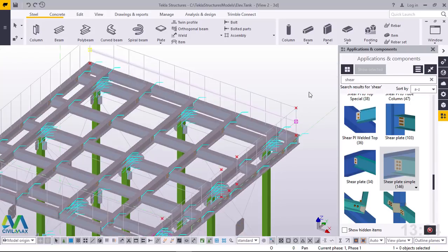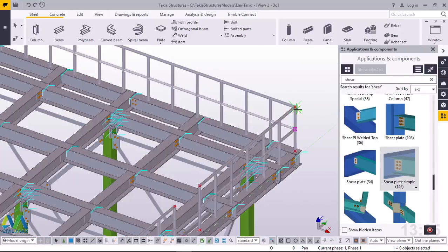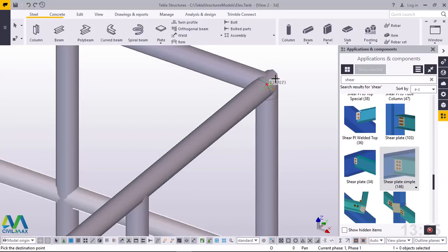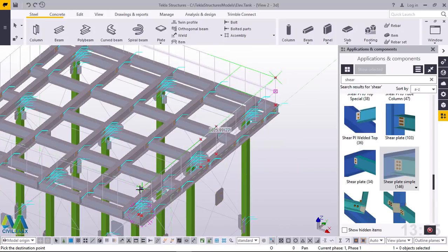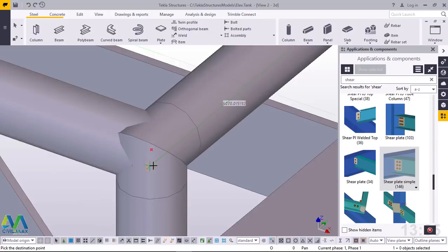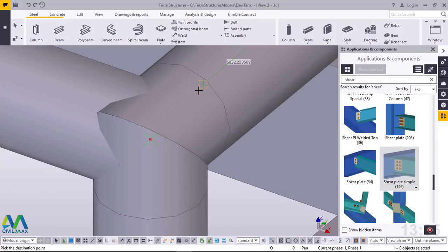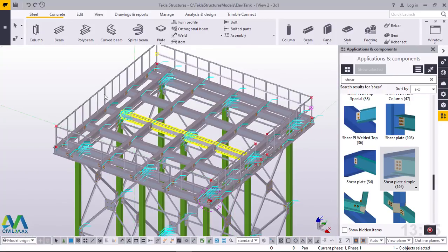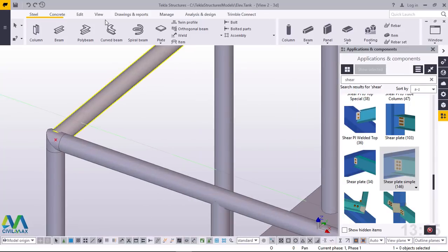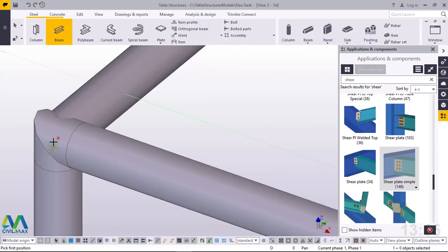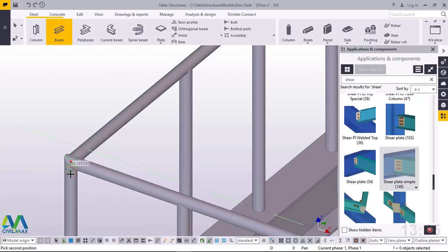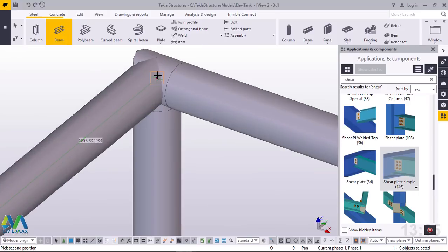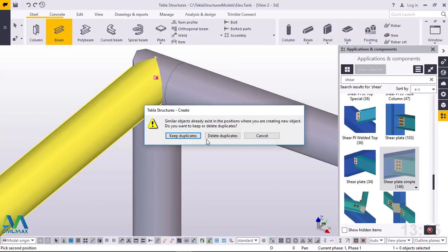and we'll do the same thing here. We'll right click and come to copy, and we'll copy it from this spot right here. Move it all the way to this end, and we'll snap it right here. Perfect. We'll click interrupt just to exit from that spot. Now we'll create another rail here. We'll click on the beam, then zoom out, and we'll snap right here and go all the way to the other end and snap right here. Perfect.